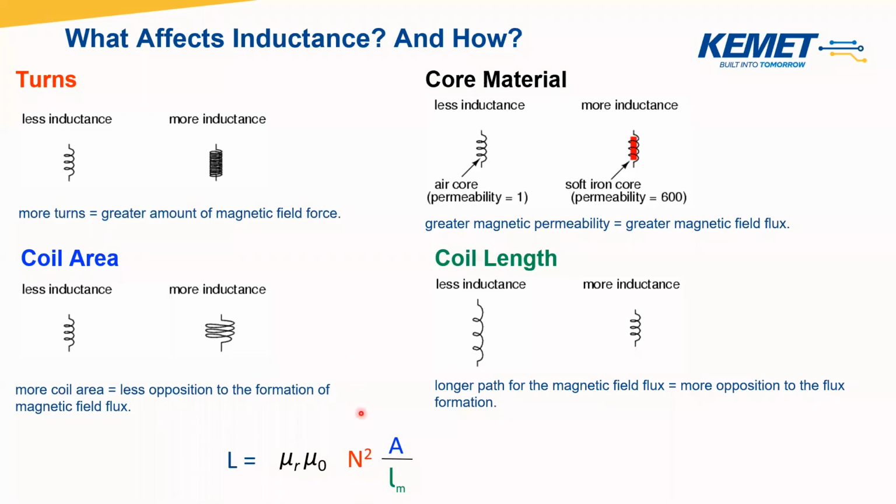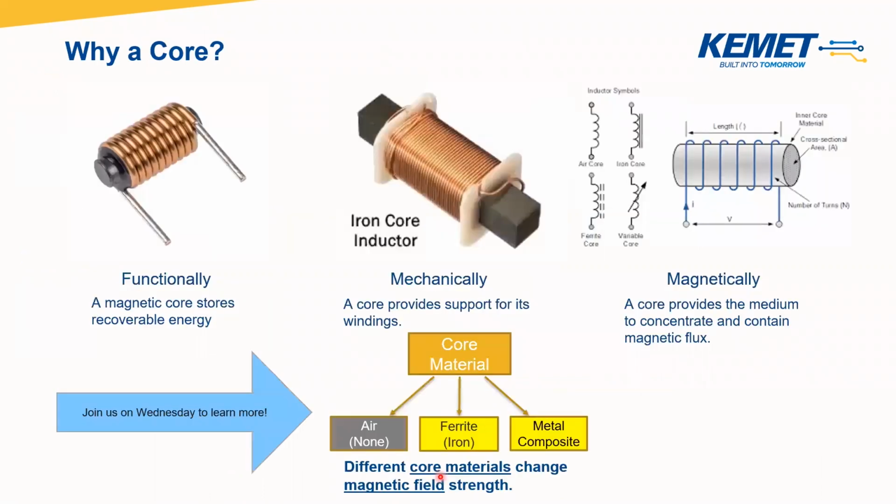Well, the more turns you have, the longer your coil is going to be, and thus you might actually end up reducing your overall inductance. So you have to be careful with that trade-off a little bit.